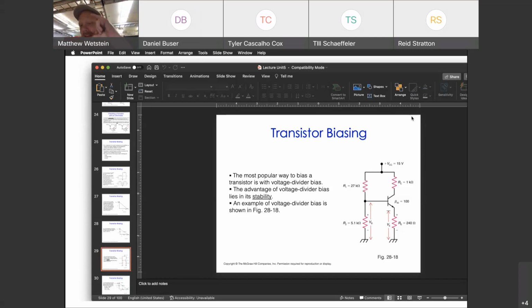Anyway, what causes the condition under which the voltage across the transistor, VCE, is 15 volts? Zero current to the base. That is correct. So if you're not applying any current to the base, then there won't be any current going across the collector emitter, which means that there will be no voltage drop across RC or RE, and therefore all of that 15 volts is across the transistor.